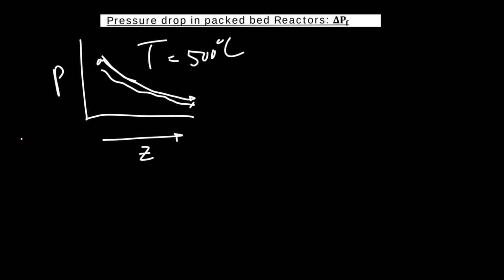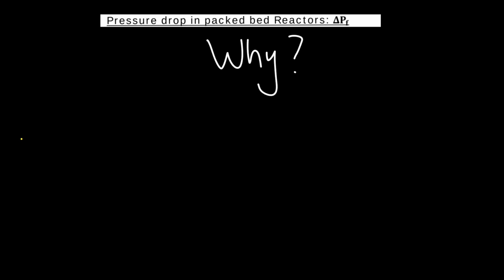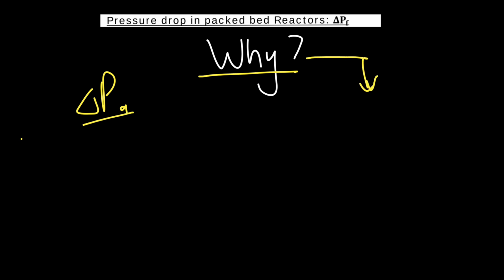If there's a drop in pressure, you must ensure that the pressure at the outlet is still higher than the vapor pressure of your components in that mixture, so that you don't have any gas bubbles forming in your fluid from that system. So our interest is more than just in quantifying the pressure drop and the outlet pressure in our system. We are specifically interested in this part of this subject in gas phase reacting systems.